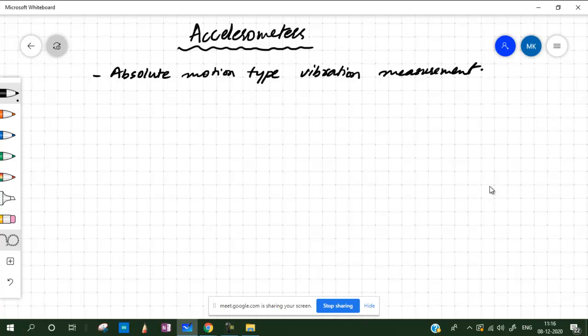We may obviously use some other strategies which can give us the measurement of the acceleration. Let's say we have discussed position or velocity measurements, which we can differentiate to get higher order terms like x double dot, which is the acceleration. But if we take position, we are double differentiating it, so the noise is amplified a lot. And if you use velocity, again that signal is differentiated and the noise is amplified. So we do have methods whereby we can directly measure the acceleration.